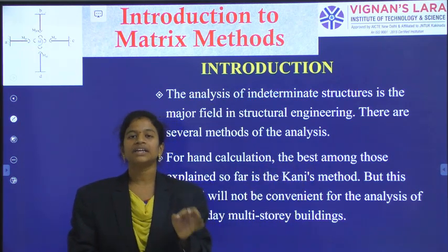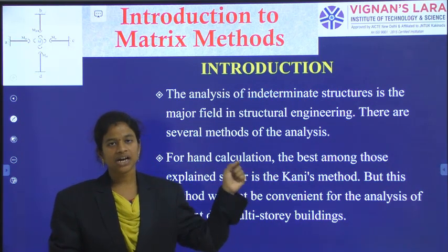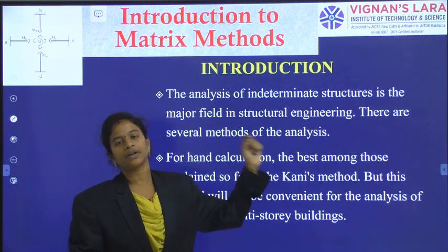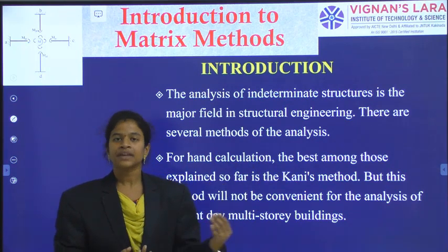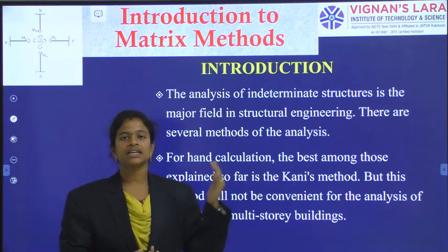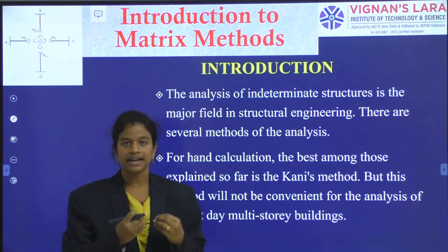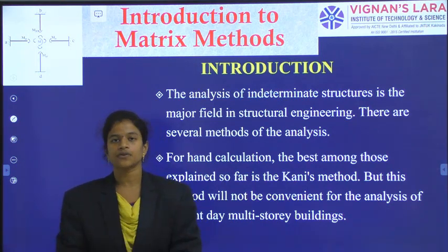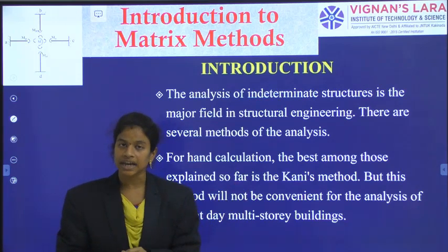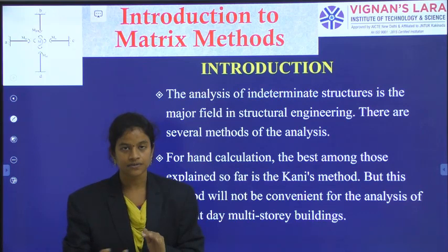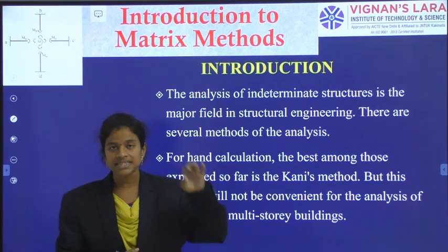So the prop reaction output has been calculated as part of the analysis of the propped cantilever beam. That is the main unknown that we calculate. And then in the case of fixed beams, we calculate the support moments and the support reactions, and then generate the shear force and bending moment diagrams. And then for the continuous beams, we calculated the support moments using Clapeyron's theorem, then analyzed the support reactions and generated the shear force and bending moment. So the complete analysis was done there.